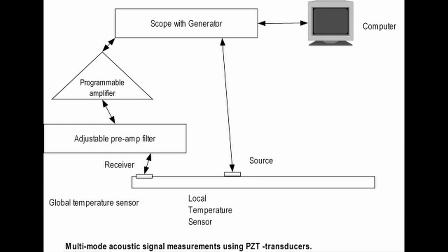Corrosion detector used with multi-mode acoustic signals, generates and receives using simple single element sensors. Changes in energy distribution over the selective modes are analyzed through signal processing to monitor material loss or addition. Corrosion effects such as pipe wall losses or solid material deposits in the pipes are simulated numerically.